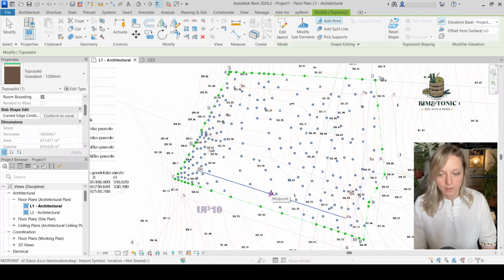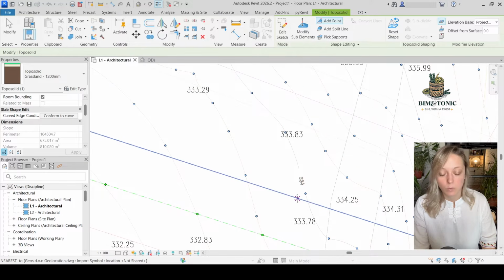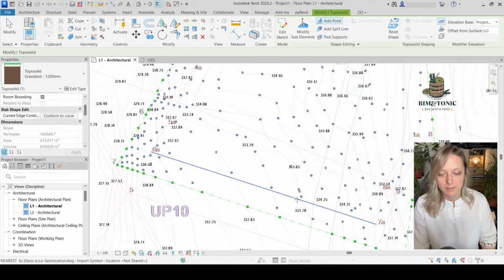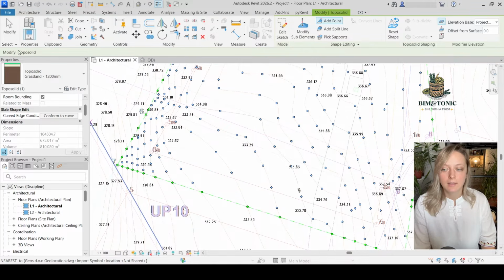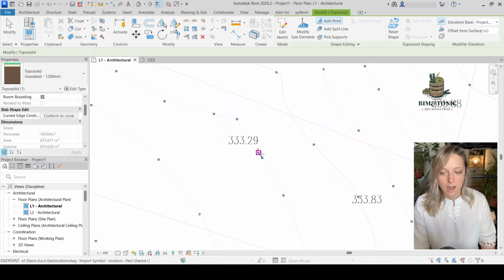What I first have to add is that you shouldn't forget about the units. What happens to me very often is I will not change my units. I will remain in millimeters, which is the default value, and I will keep adding these heights, which are in meters, and I would get a mess. This is something that happens to a lot of people. They will simply forget their units, and this is something that you should be very mindful of. Essentially, the heights that I see here in these numbers are in meters, and as I said, I haven't yet changed the unit of my file, and my file is now in millimeters.